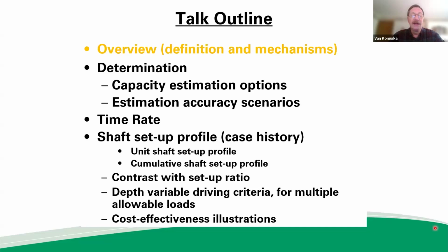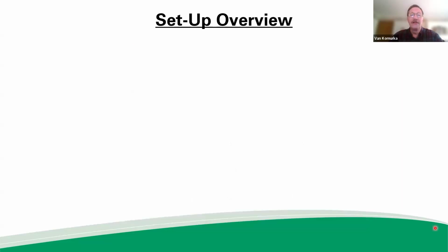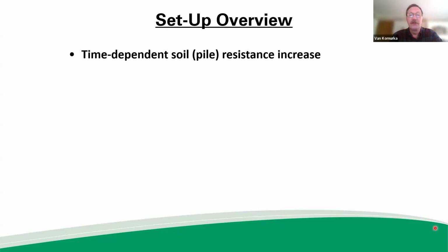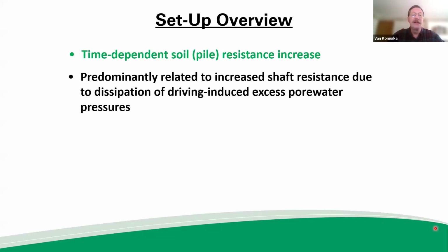So let's first look at the definition of setup and some of the mechanisms associated with it. For those of you who may not be familiar, setup is a time-dependent soil resistance or capacity increase after driving a driven pile. Often we say the pile sets up after driving. The pile doesn't set up, the soil does, but it's kind of an interchangeable term, pile setup, soil setup. It's predominantly related to an increase in shaft resistance after excess pore pressures that have been developed during driving dissipate.